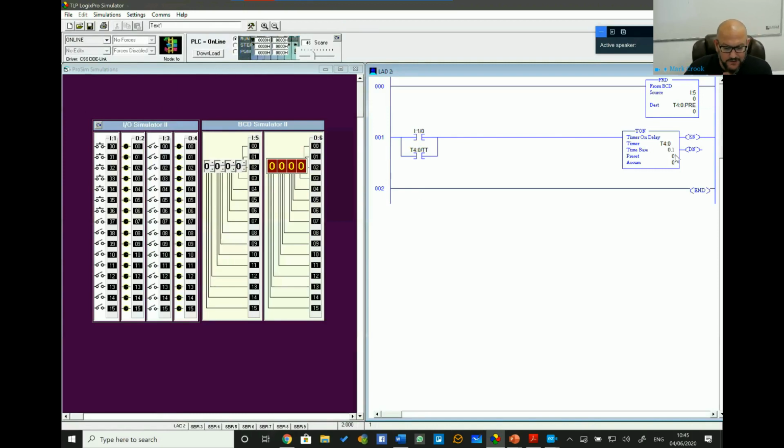At the moment, as you can see here, we have no preset in the timer. As I move through the BCD thumbwheel, you can see now I'll give it the value of 1. So 1 has now moved to the timer. If I move the second digit of the thumbwheel, it now has a value of 11. So let's just trigger that by pressing the button, and you can see the timer there running for 1.1 seconds, because it's 11 times 0.1 second time base increments.